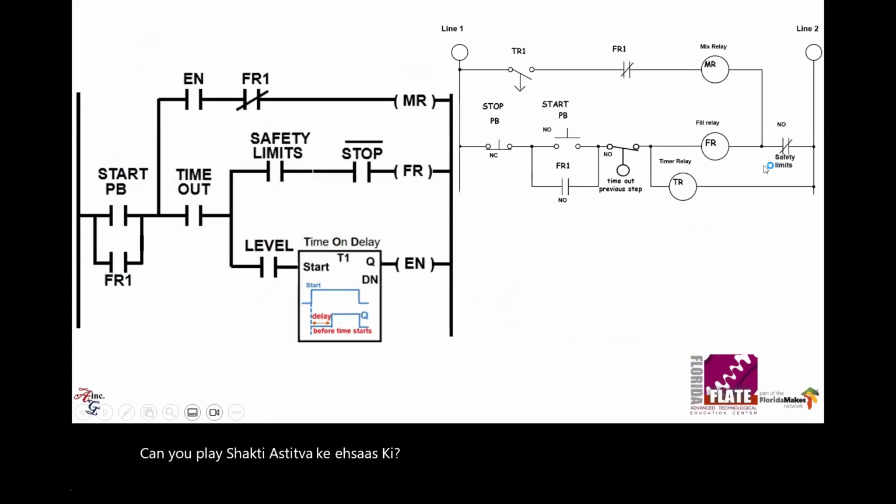And finally, the program. And we can stare at this and work on this, right? A big mistake you can make is to just try to rewrite this. For a starter, this symbol right here was the intent, but it wasn't done with a delay off. It was done with the delay on, so that you could accomplish what you wanted.